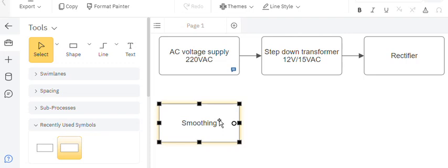So what exactly is the capacitor doing? The capacitor is going to do one thing, smoothing. And it does it in two ways. Number one, by ensuring that anything that looks like AC passes through the capacitor and goes to the negative side in order to go and recycle at the transformer end.